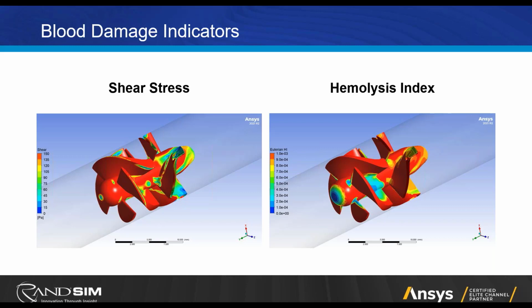And you can see, obviously, red is high, so a very large amount of the turbo surfaces are in excess of our 150 threshold, which is normal. You expect that to happen. We try to minimize it, and we try to reduce the amount of recirculation and stagnation that occurs. And you can see the blue area is in the trailing edge and the tail of the diffuser there on the right side of that image.